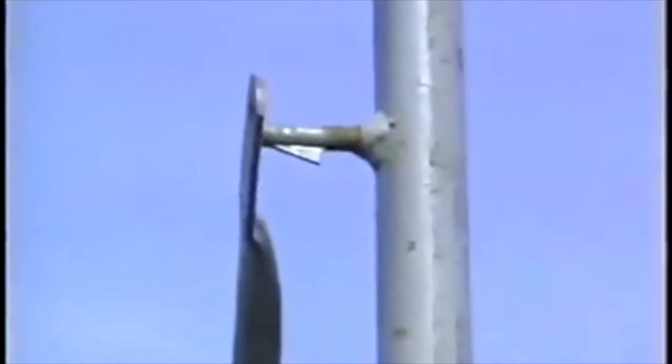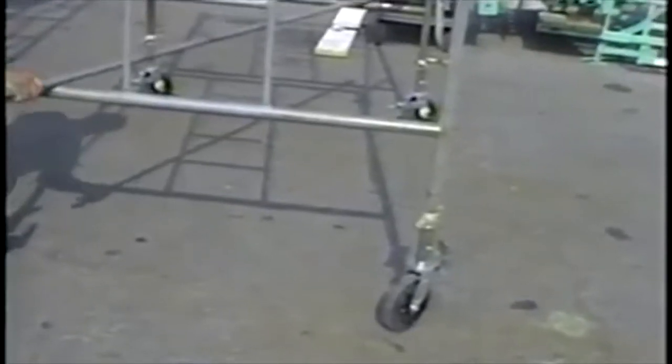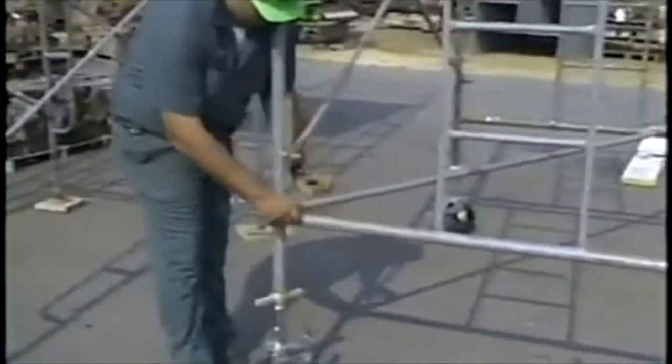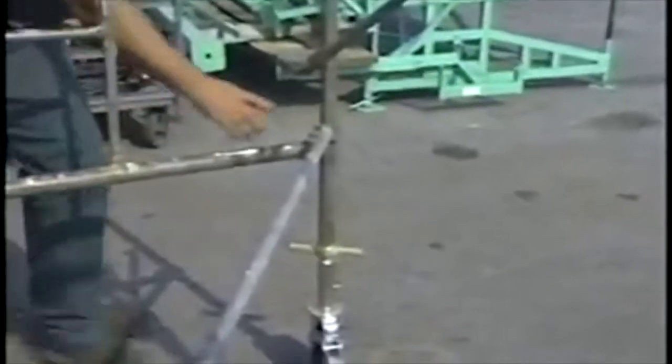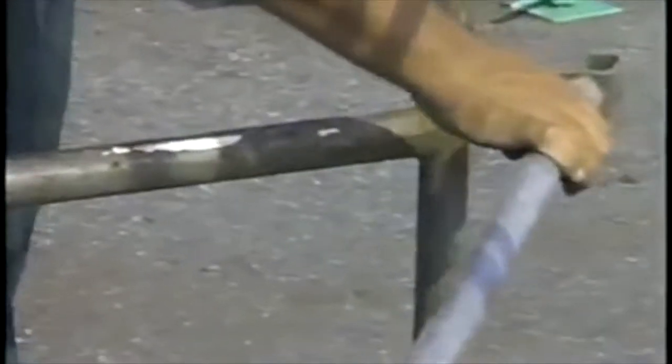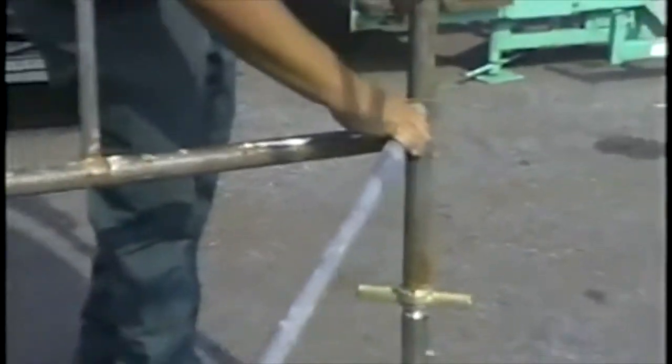Mobile scaffolds, which are supported by casters, must consist of cross braces and diagonal braces secured laterally to the vertical end sections or members to maintain stability. The cross braces and diagonal braces must be of a length that will automatically square and align vertical members so that the erected scaffold is always plumb, square, and rigid.